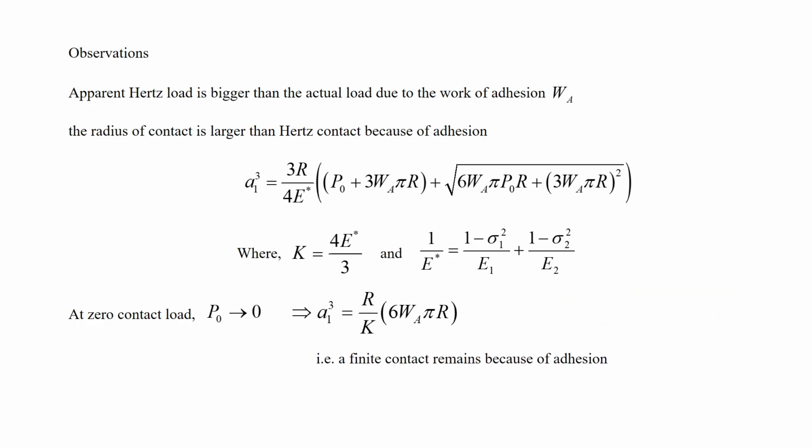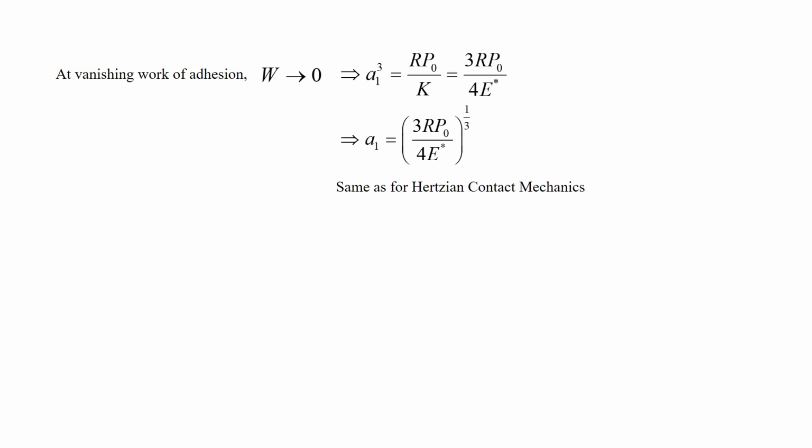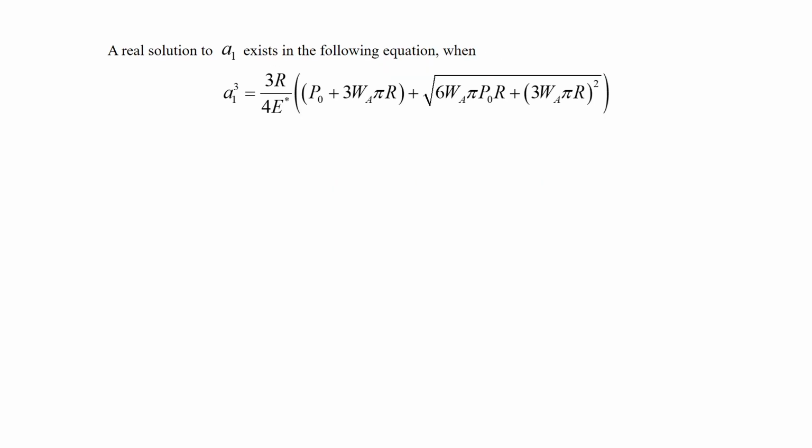So, finite contact radius remains because of adhesion and vanishing work of adhesion, that I have already described. With this condition, we get back the Hertzian contact mechanics, the contact radius for that purpose. Now, there is another interesting point here: for a real solution for A1 to exist,